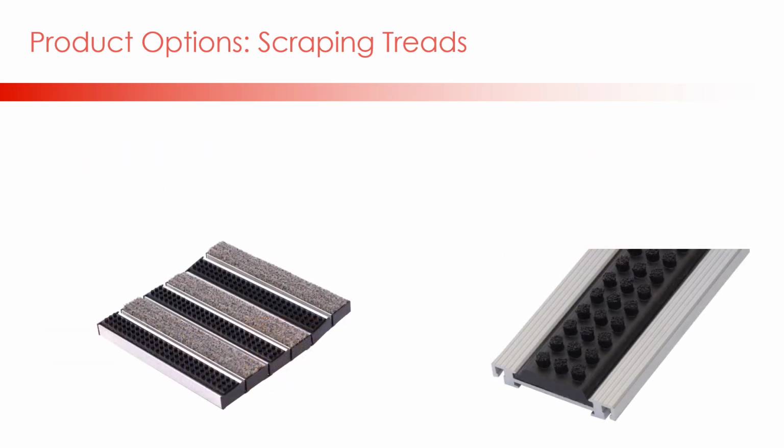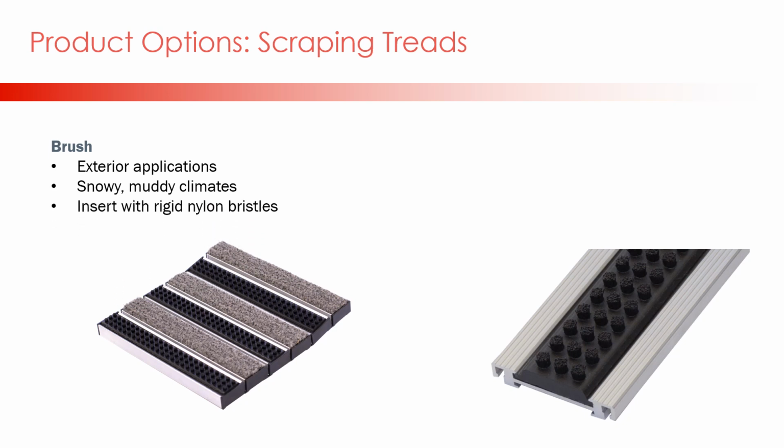A recent introduction into the United States market is brush. This product has been used extensively in Europe and is ideal for exterior applications in snowy, muddy climates. The brush treads are made with rigid nylon bristles, 9 tufts per inch, with each tuft containing 80 bristles.